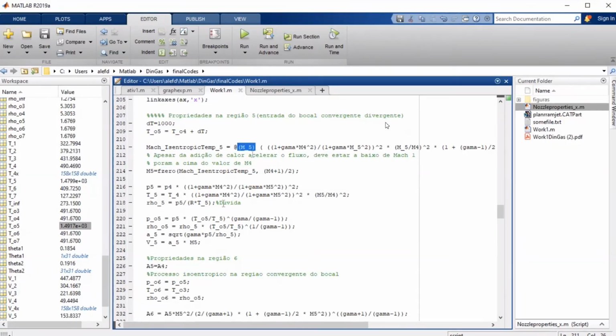Is there a way to calculate how much stagnation temperature ratio it can add before reaching Mach equal to 1 after heat addition? You put in two parameters. There is nothing to solve. You just put the Mach number before heat addition and the Mach number after heat addition on the right part of the equation. Then on the left part of the equation, you will see the limiting, maximum possible temperature ratio that can be realized in this flow.